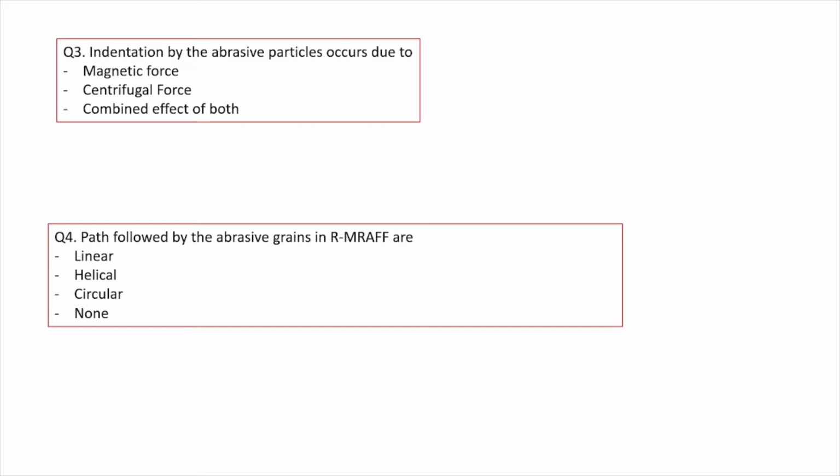So the combined effect of magnetic force plus centrifugal force causes indentation by the abrasive particles. One more thing: the cutting force is also there, which is the resultant of the axial force and tangential force.